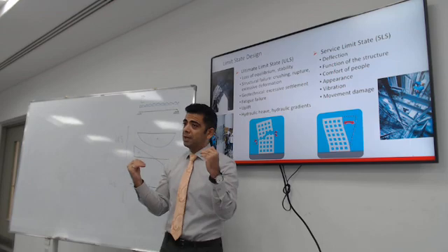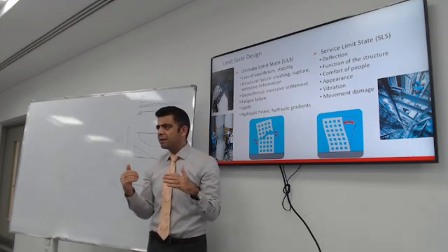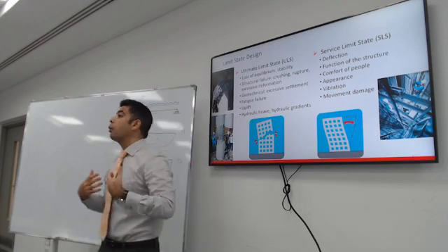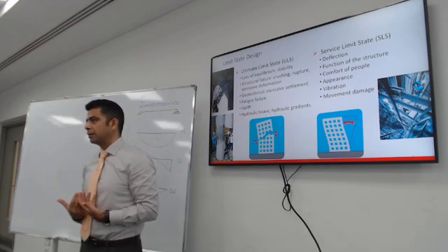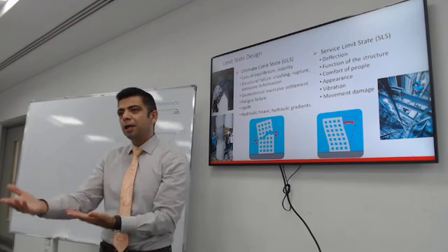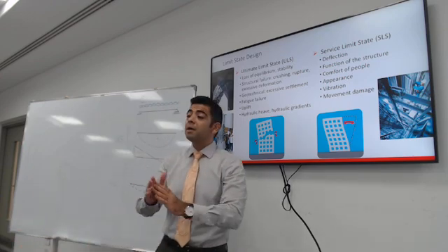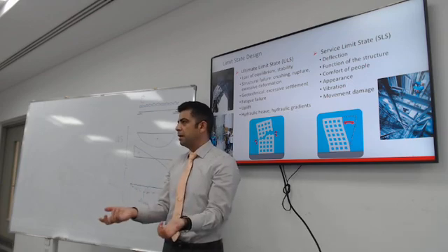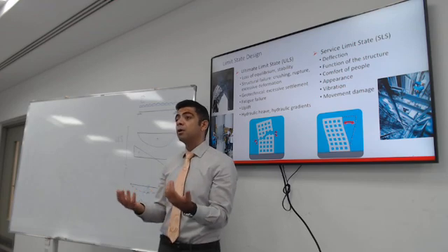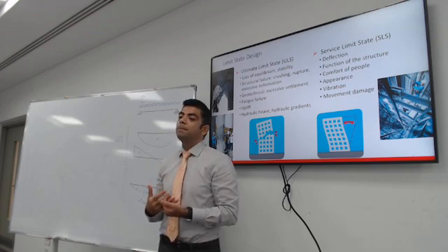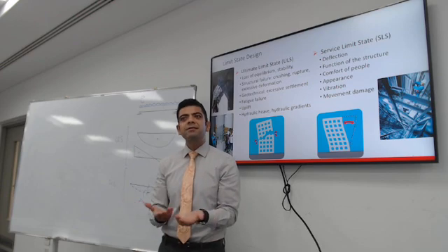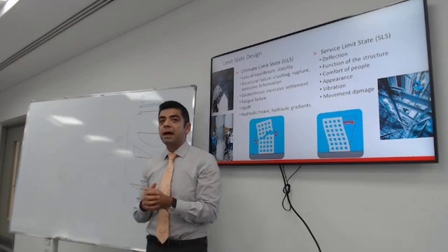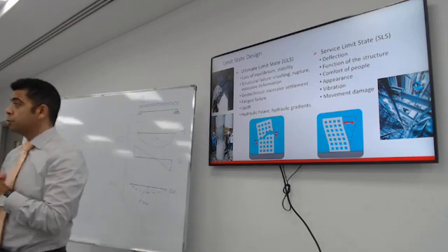There is another state that is way less than the ultimate load, way less than the maximum capacity. I want to know, under our normal weight, under the normal use, the everyday use of this classroom, is the floor gonna vibrate too much when we walk on it, or is it gonna be comfortable? It has nothing to do with safety, it has to do with comfort of the users and the serviceability of the building. Hence the name, the service limit state. And I'll talk about the load factors that are associated with that.